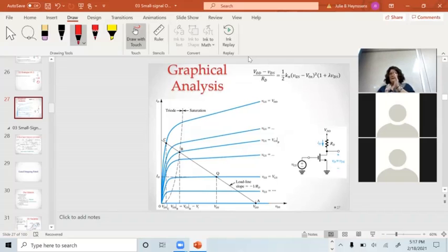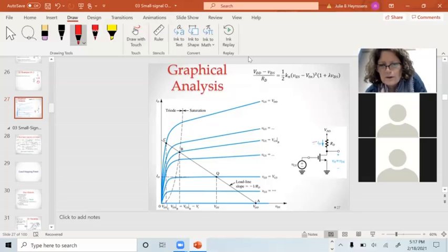Now, as long as the resistor is behaving like a resistor and you have not let the smoke out, Ohm's law works. So for this resistor, if I have 0 current going through the resistor, if ID equals 0, then that means V out is VDD. I plot that point on this line. ID is 0, V out is VDD.